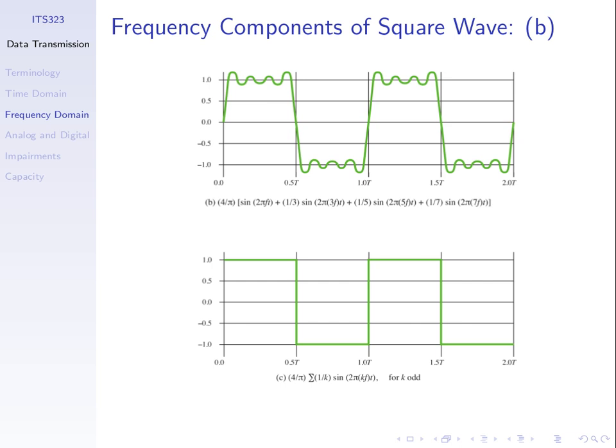What we're going to do is go through some examples which look at, okay, what if we use a different number of components? How does it impact upon bandwidth, frequency and data rate? We want to maximise data rate, and normally we want to minimise bandwidth. We'll talk about why shortly, as we go through the examples. And as the person who designs or chooses the signal to be transmitted, they normally want to choose a signal which can be used to accurately represent the data.